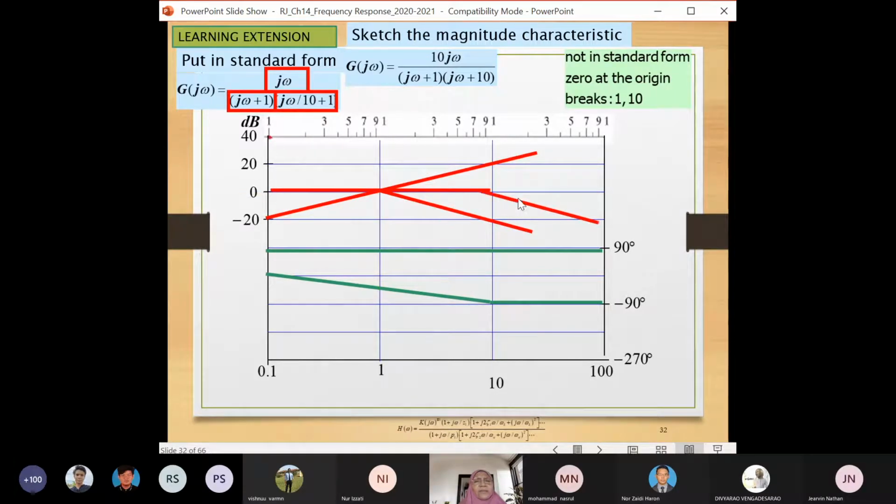Then it goes down. For the phase plot, it runs through the corner frequency, spanning from 1, which is 1/10 of corner 10, and 10 times at 100. So with 45 degrees per decade, the slope of this phase plot. So flat prior to that, and then flat above it.